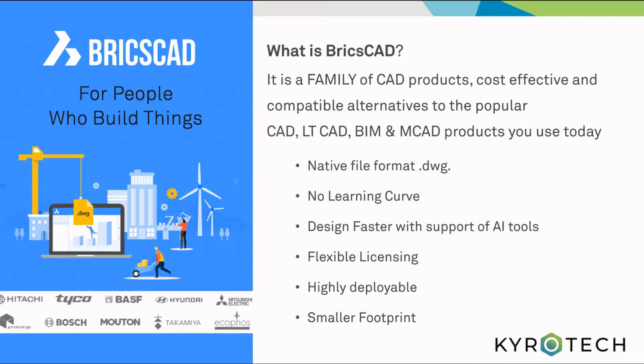Moving on, we have no learning curve. BricsCAD believes whatever knowledge you currently have with your current solutions needs to be reused. For example, all your commands, templates, and customization files can be directly imported into BricsCAD and you can start using it directly. For example, the command for line in BricsCAD is L. For polyline, it is PLINE. For circle, it is C. For mirror, it is MI, and so on.